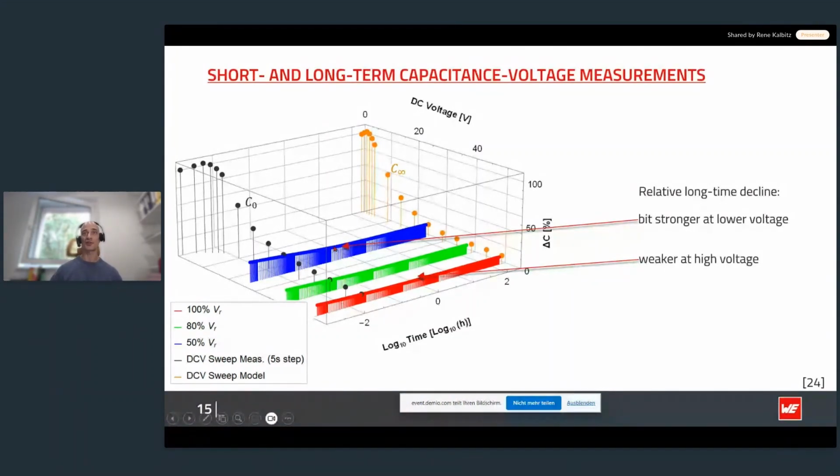The long-term effect is certainly measurable and it may have an effect, but it is less significant than the immediate effect. Most class 2 MLCCs have production tolerances of 10 or 20%. Generally speaking, the long-term DC effect is about or even well below those tolerances anyway. So in some representations, you may find them normalized to those initial values, which then gives the impression of a significant capacitance decrease.